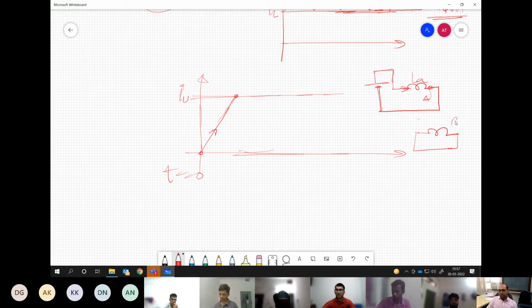Due to the resistance in the coil, it will decay slowly. But you fix the lower limit also, so while it is decaying, it cannot go below this lower limit. The moment it touches the lower limit, again you switch back to mode 1.